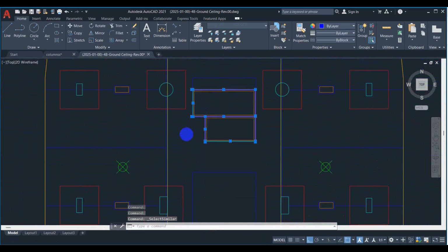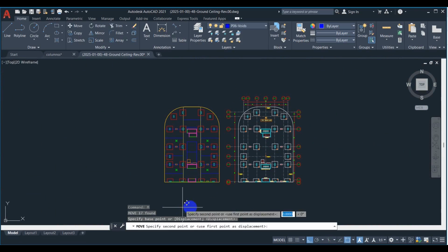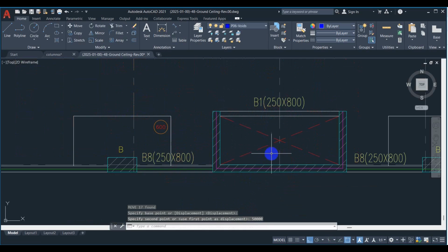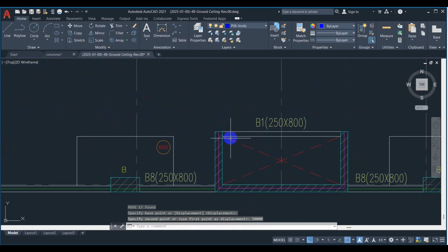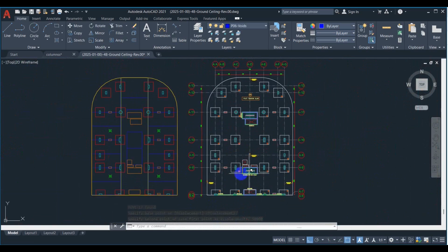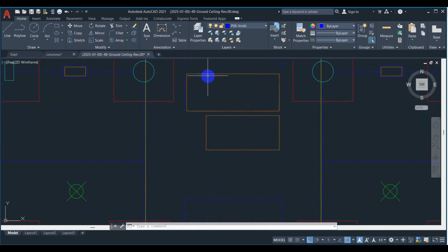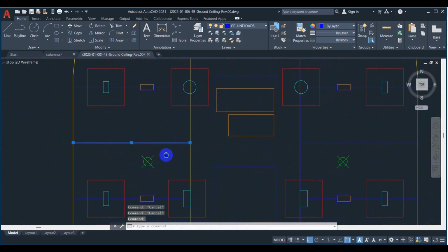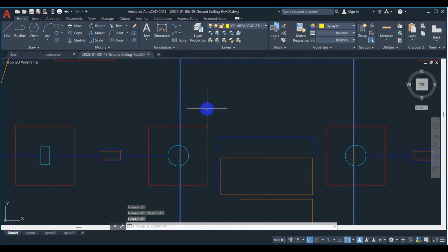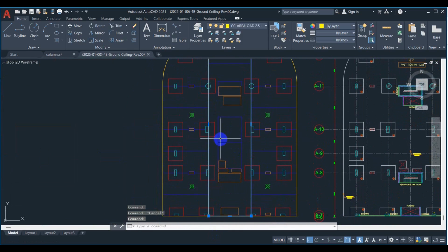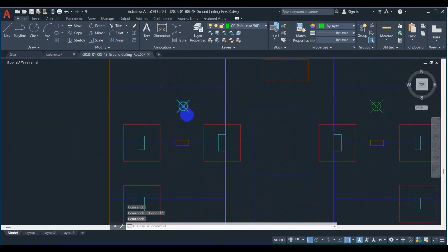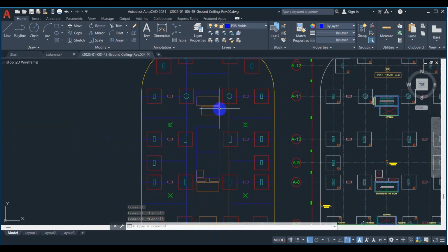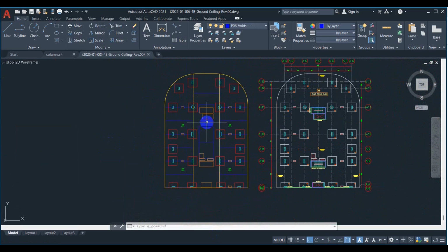Let's see how, by putting this into it. See, it represents the center line. The same for beams, and the openings are polylines. If you have a line load, it will be a line. If you have an area load, it will be an area polyline, and point loads are points. So it's clear and easy, without any complicated things. Just follow the DXF rules.